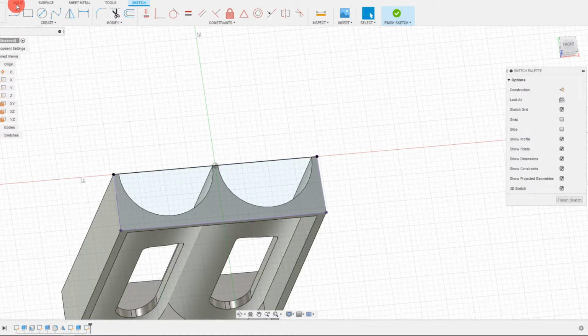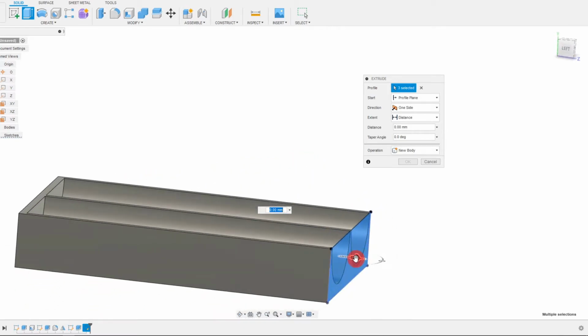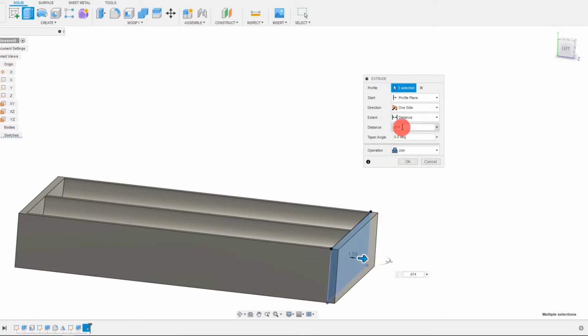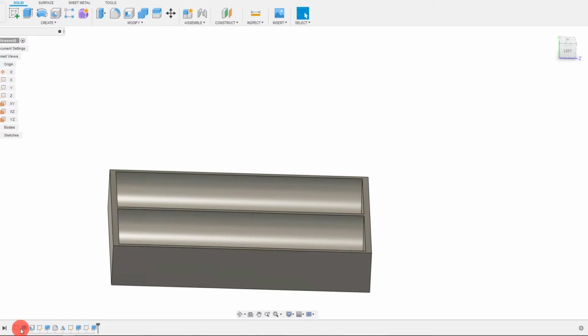And let's extrude. Except like we learned from before, we want to extrude in. That's a join feature, and it's going to be D14. So we could do negative D14, and that's a join operation. Now, as you can tell, we lost 2 millimeters from this operation.